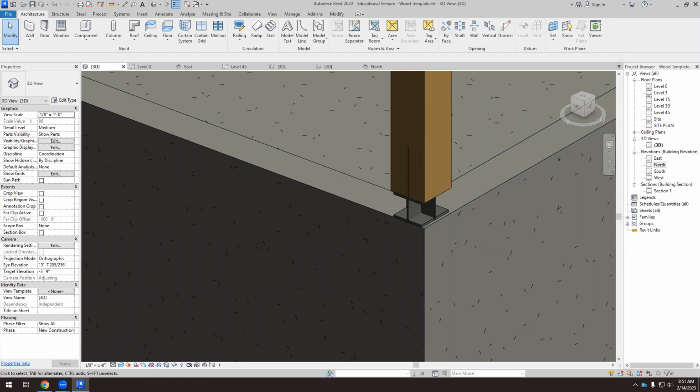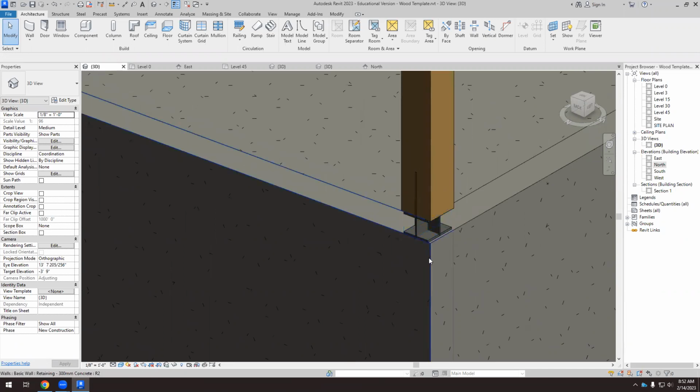Okay, so well, nobody does it. But that's the right way to do it, okay? Because we cannot press wood on concrete directly. We need this transition. It can be this one. I have found this, but there are other solutions. So, there's something to connect the wood to the concrete. So we need a steel element in the middle of these two materials. Okay.